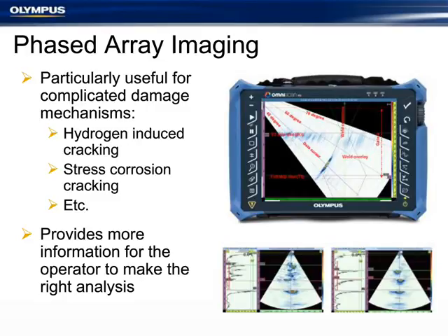It gets even more powerful with some of those hard-to-characterize damage mechanisms that are branching, like stress corrosion cracking and hydrogen-induced cracking. These types of things are somewhat easy to flag by saying, hey, we have a problem, but it's really hard to characterize how bad the problem is. What's the deepest crack? What's the highest branch that's coming out of a crack?